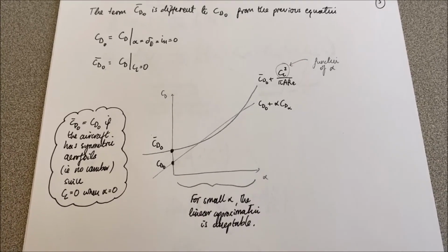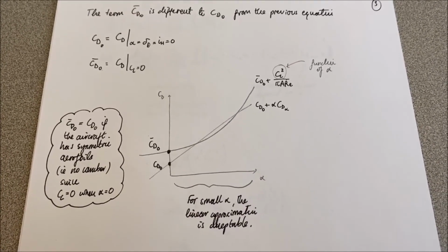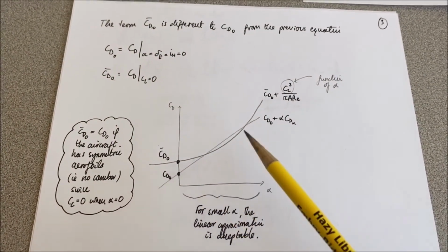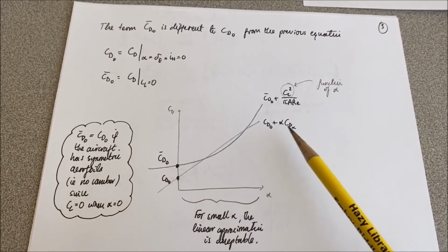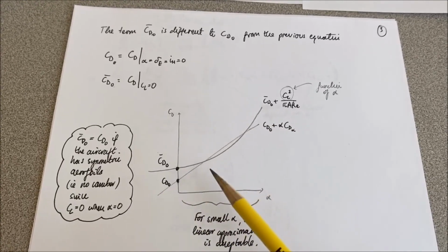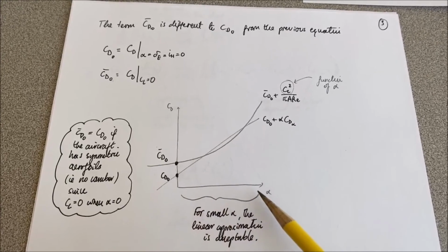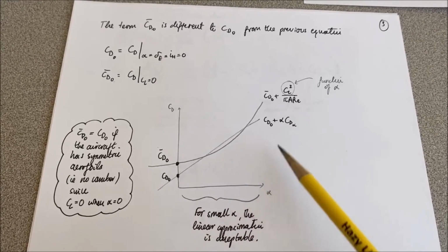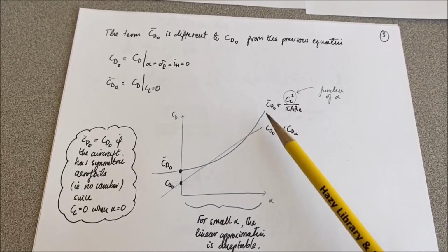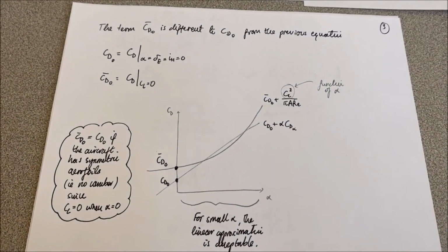So one assumption that we can make is that for small alpha, these two things are close enough that we can just take the linear approximation, and that's going to become acceptable for our particular region of angle of attacks that we're going to consider. Obviously, as we increase angle of attack further, these two lines are going to get further and further apart.